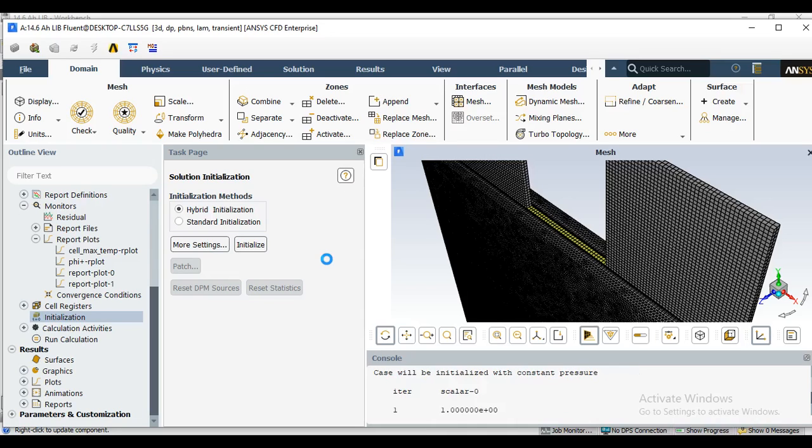For the boundary conditions, you can use different values for the outlet. You can specify outlet pressure. But in this simulation, the aim is not checking all the boundary conditions. So in another simulation that you're going to have in the future for validating an experimental situation, you can use different values for the boundary conditions depending on your experimental conditions.